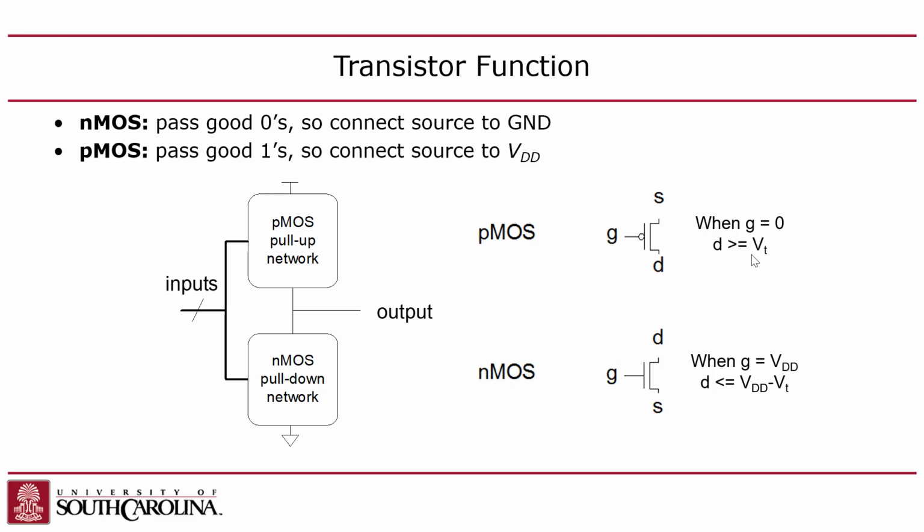So transistors are switches. You can make gates by essentially connecting the switches in series and parallel to create paths that can be on or off with certain combinations of gate values. You guys with me? So if you put two NMOS transistors in series, their gates have to both be on in order to form a path through that network. You guys with me? It's just two transistors in series, and because they're in series, they both have to be on for the whole network to be on, right?